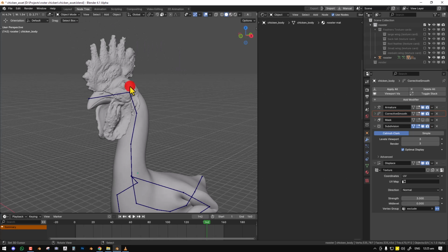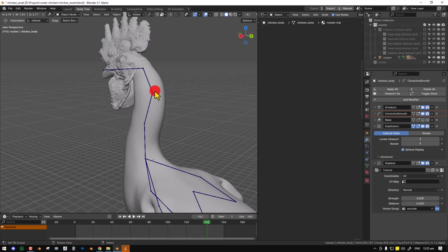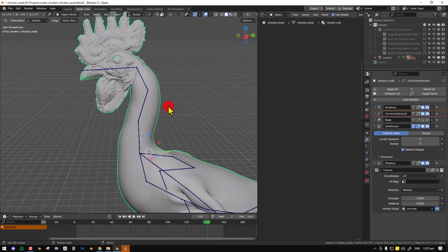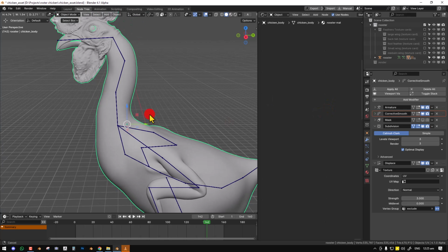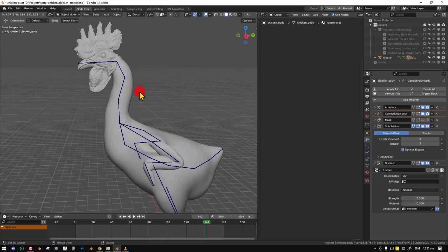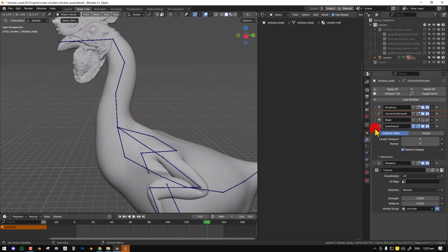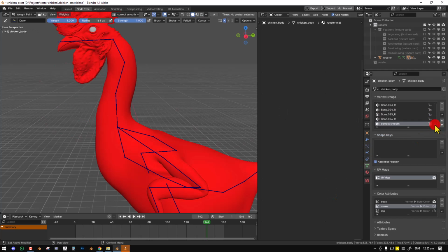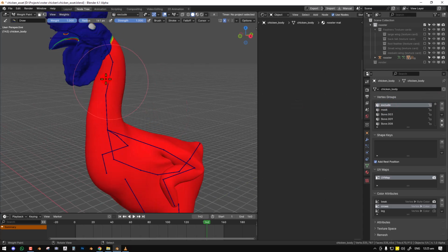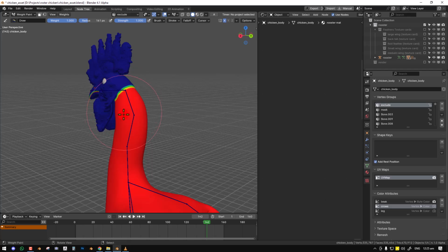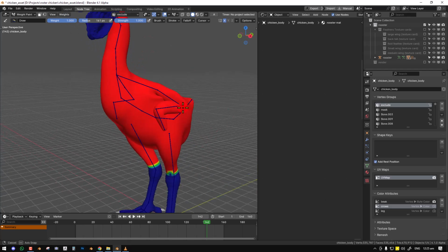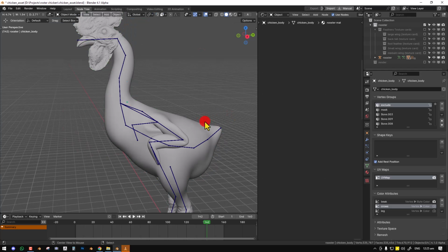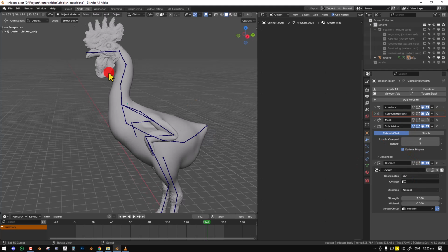But also one thing I learned working with geometry nodes hair is that when you're trying to animate it or use the surface deform, and you have displacement, sometimes it tends to give very weird results. So I used a vertex group to exclude certain regions. If we go here, I excluded certain regions where I wanted to paint in the feathers, to avoid any complication. And it all worked out since those areas will not be visible. And so that's basically the mesh setup.